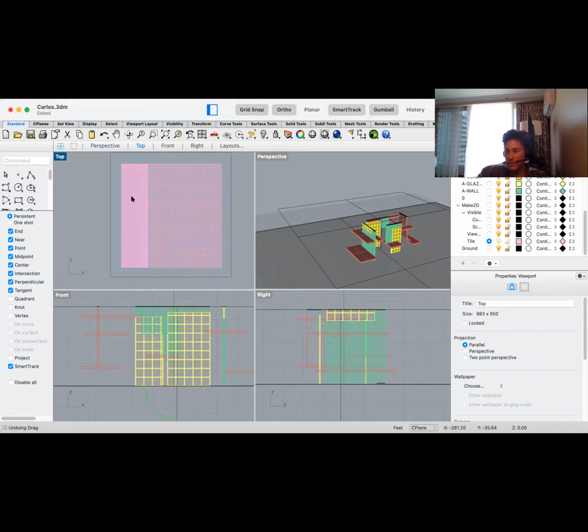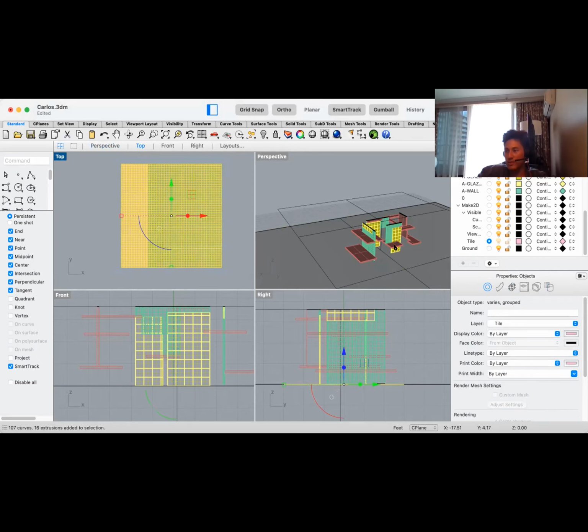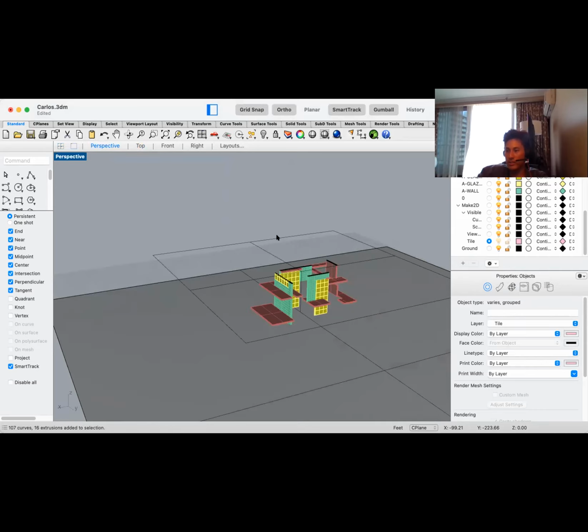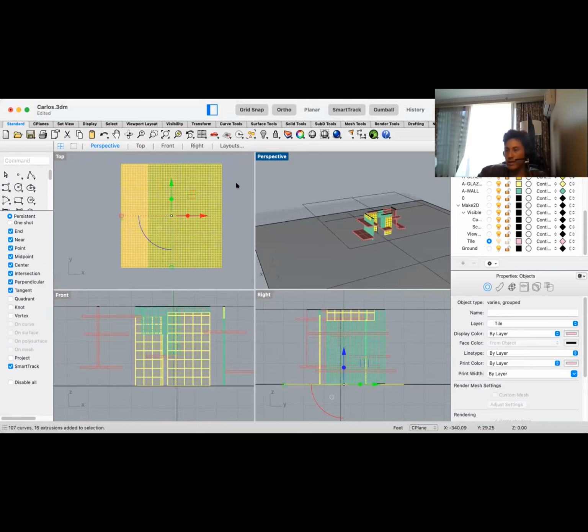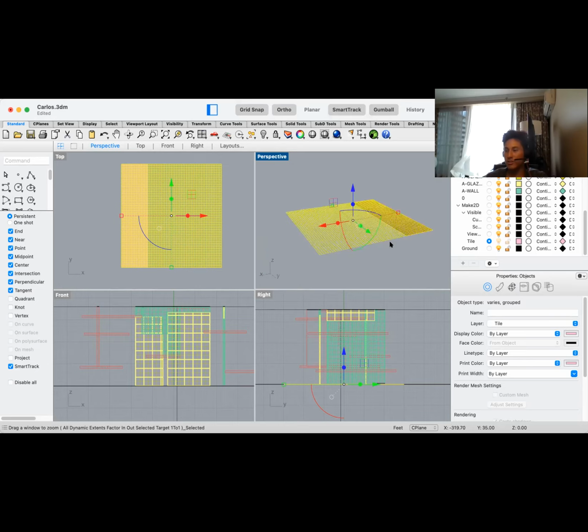Okay, now in the perspective view, you have to click the tab that says perspective at the top left. Yeah, there. Don't double click it, just select it once. Or just, okay, double click it now, so we can see the four. Perspective? Yeah, double click that. Go back to the four. Then, you know how that tab is now blue? I wanted to activate that tab. So when we type ZS, don't deselect anything. Just type ZS on your keyboard. Do you want me to select? No, type ZS on your keyboard. Oh, okay. Sorry. You're fine. And then enter, and it should zoom into that.